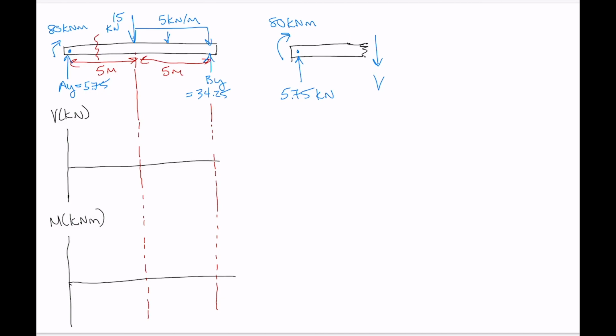Put the moment in the positive direction according to our sign convention. So that is bending the section into a smiley face configuration, so it needs to be an internal moment that's oriented in that direction. And then again, no internal normal force is necessary because the sum of the forces in the x direction is already equal to 0.